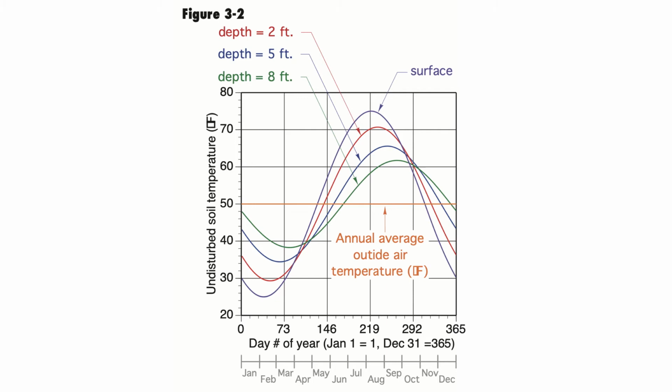As it pertains to vertical boreholes, typically from 30 feet to about 200 feet below the surface, the soil temperature is a relatively constant 55 degrees Fahrenheit. These are important factors that ground source heat exchanger designers take into consideration. A horizontal slinky loop that is only 5 to 8 feet deep is not going to perform the same as a vertical borehole that has been drilled to 200 foot deep.